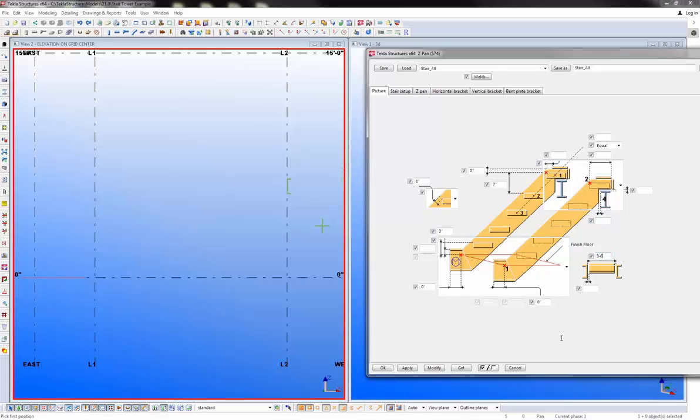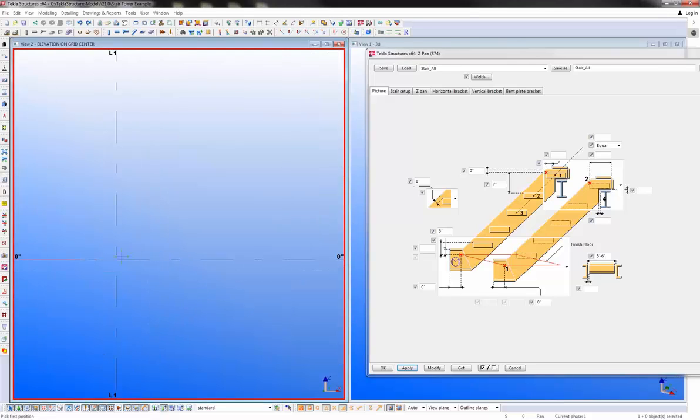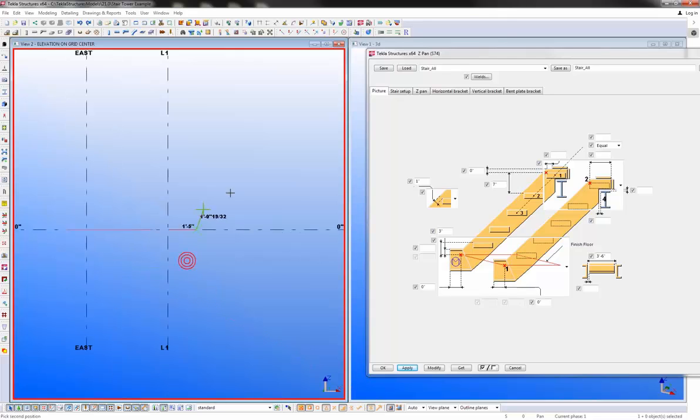However, when you can, it's always a good idea to take advantage of the options that are available. So I'm going to set this stair to be 3 foot 6 inches wide. And I think we'll go with that for now. I can always adjust the settings after it's in. So I'm going to start off down here. Again, these are my nosing points that I've already laid out. So I'm going to turn on some of my snaps here. I'm going to come over 1 foot 5.